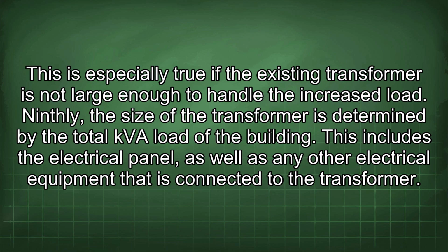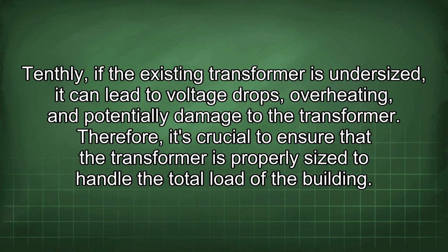Ninthly, the size of the transformer is determined by the total kVA load of the building. This includes the electrical panel, as well as any other electrical equipment that is connected to the transformer. Tenthly, if the existing transformer is undersized, it can lead to voltage drops, overheating, and potentially damage to the transformer. Therefore, it's crucial to ensure that the transformer is properly sized to handle the total load of the building.